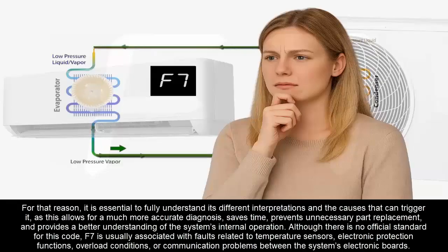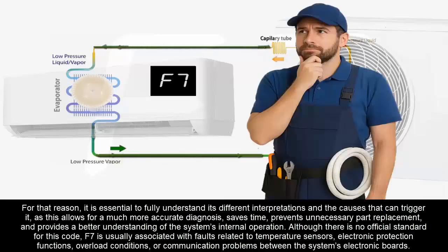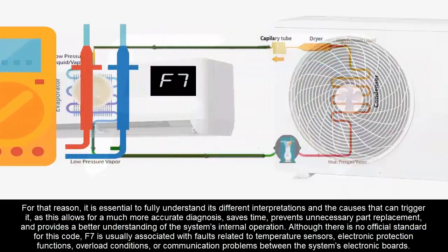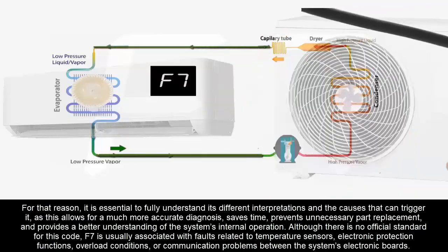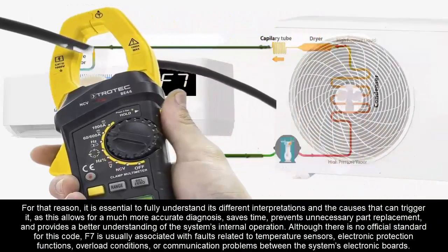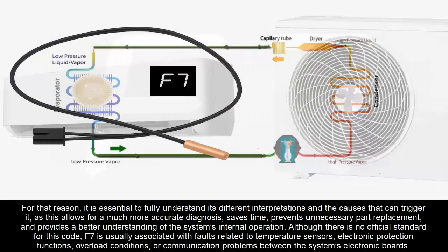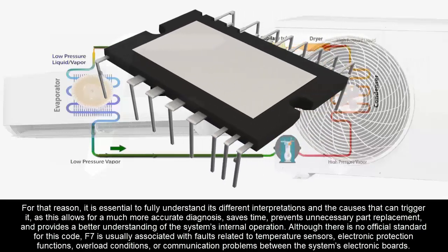For that reason, it is essential to fully understand its different interpretations and the causes that can trigger it, as this allows for a much more accurate diagnosis, saves time, prevents unnecessary part replacement, and provides a better understanding of the system's internal operation. Although there is no official standard for this code, F7 is usually associated with faults related to temperature sensors, electronic protection functions, overload conditions, or communication problems between the system's electronic boards.